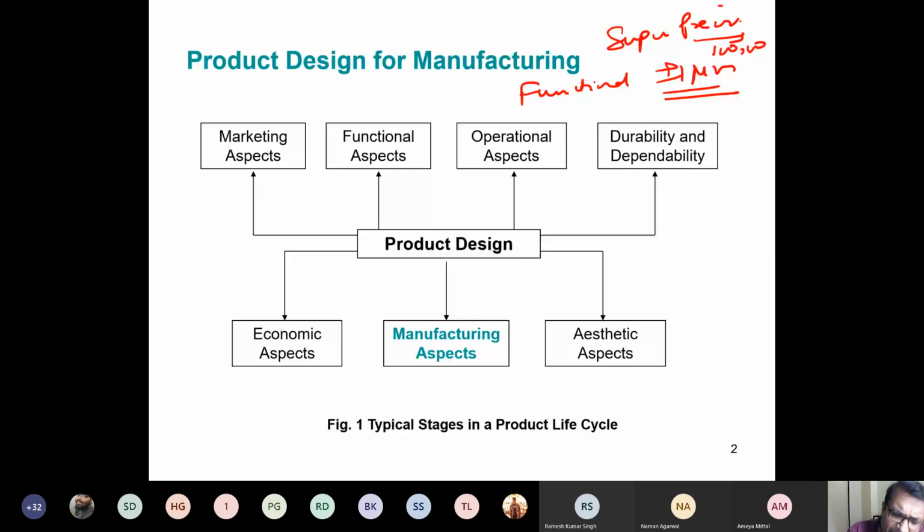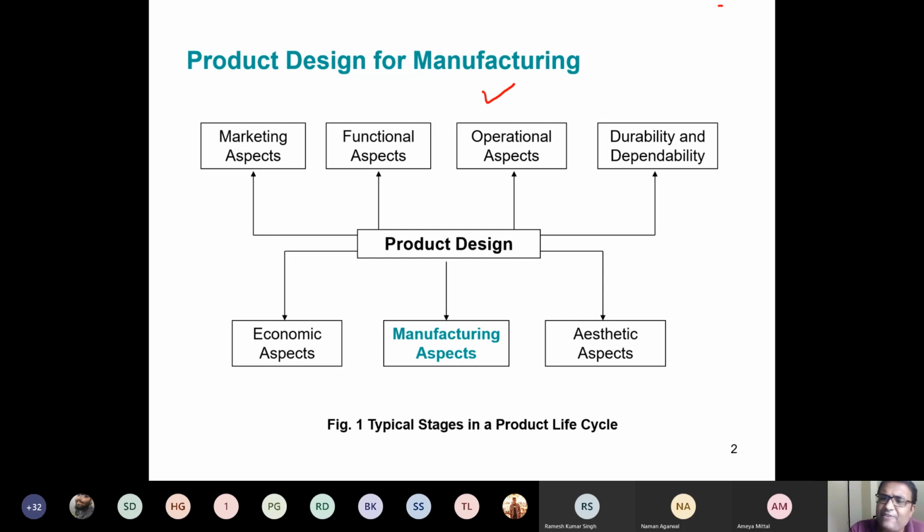But where you have a functional requirement, the answer is the functional requirement. Unless and until there is a functional requirement, I will never ever give a tight tolerance. Never ever. As an engineer, my first idea should be, yes, fluidics. In some cases, you need tolerances, but microfluidics, typically there's no mating parts there, right? So you just have to make accurate channel. So if there is a mating part, that's where your tighter tolerances come.